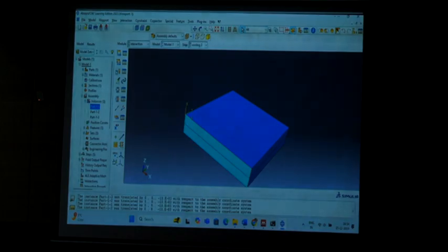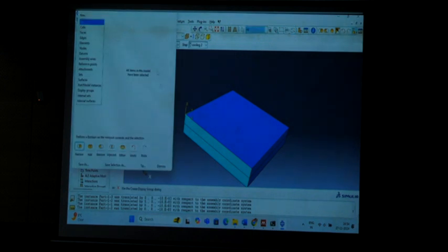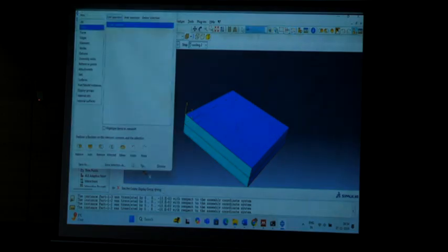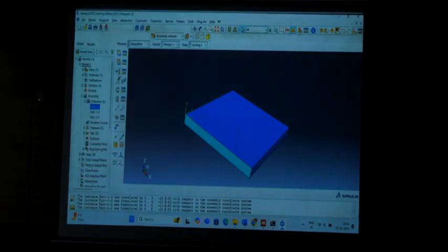In that case, if you can see here, we have the option creator. Since this is working on cells, we will say this bottom layer we are removing, because it should be having some gap, so that we can choose the interfaces of those two. We will just click on remove. It removed the bottom layer.